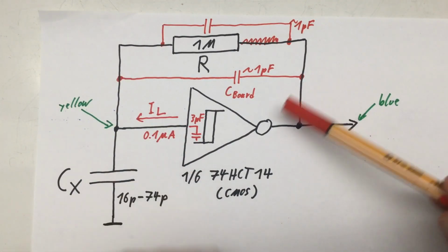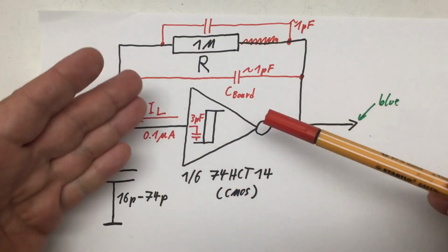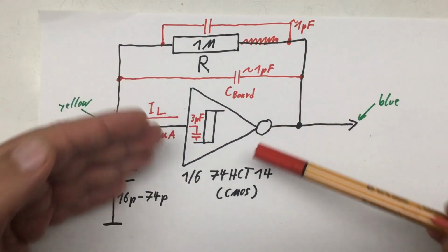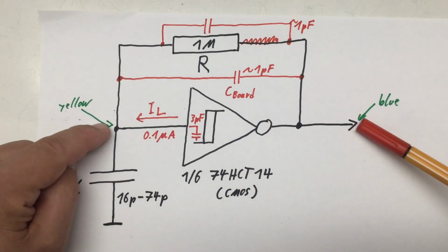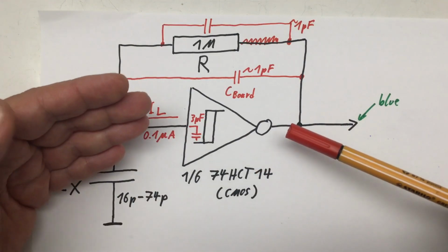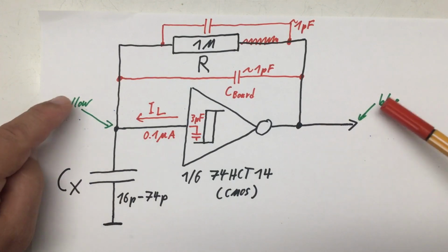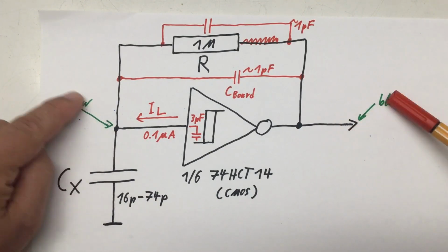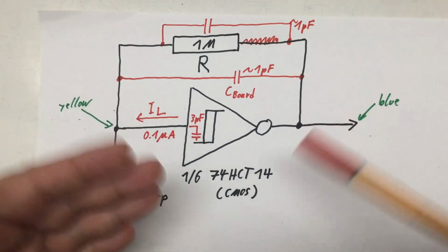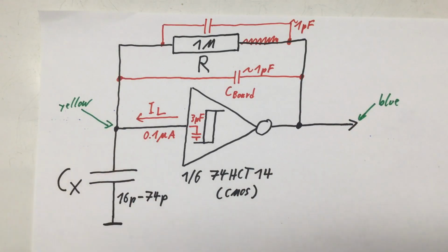In the previous video, we talked a lot about how parasitic capacitances are messing up the behavior of our oscillator. And we just saw that just by removing the oscilloscope probes, our frequency jumped from 6.7 kilohertz to 20.4 kilohertz. And I didn't even mention the influence of the oscilloscope probes in the previous video. So here's some errata/addendum to the previous video.